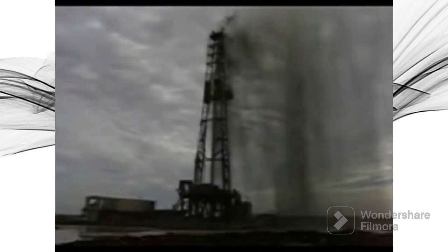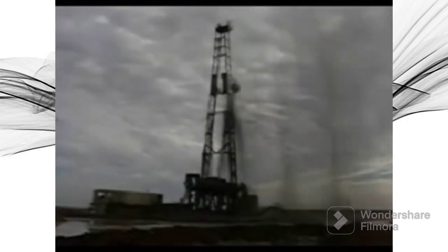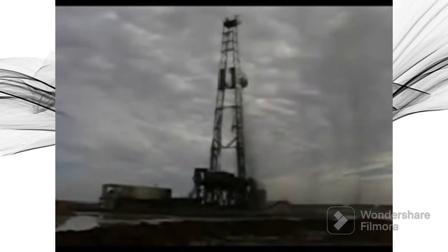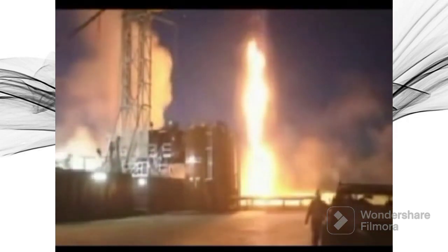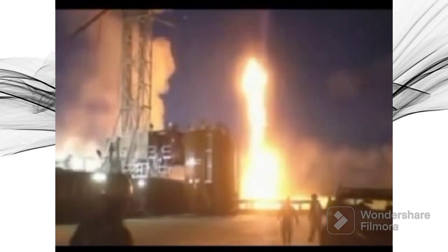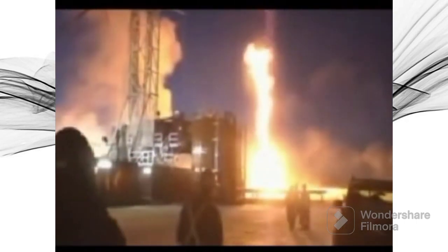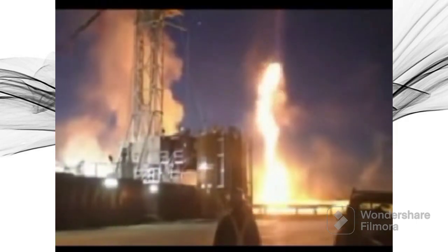Other BOP maintenance practices to promote oil well safety include removing all the metal fragments in the BOP using a downhole magnet, cleaning out the mud in the equipment to minimize the risk of leakages, greasing all moving parts in the BOP equipment, and last but not least, close monitoring of all the drilling and completion activities with utmost care.